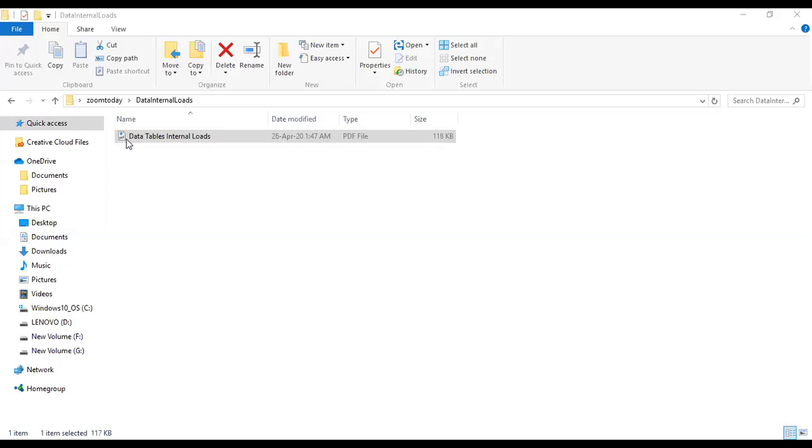The floor area is 10 to 15 meters square. So you assume that for 10 to 15 meters square, there will be one occupant in an office building. If there is a big room and there are more than one officer sitting there, every officer will take 10 to 15 meters square area. So total floor area of that building you can divide by 10 or 15, and you will get the number of persons sitting inside.